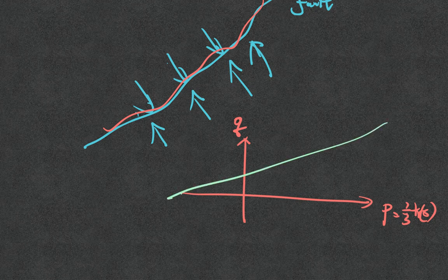Meaning that the more pressure I have, sorry, this is not the pore pressure, it's the solid pressure. The more pressure I have, the harder the shear, right? It's just like my hand. If I push really hard, I find it very hard to shear. If I don't have any force, I have a lot of freedom to move sideways, right? Just like against each other. Now, previously we are stable, we're here. Maybe I'll put a different point. We're here, very, very stable. I never reached the failure envelope. This is what happens in failure. So when you hit this, the whole thing slides.